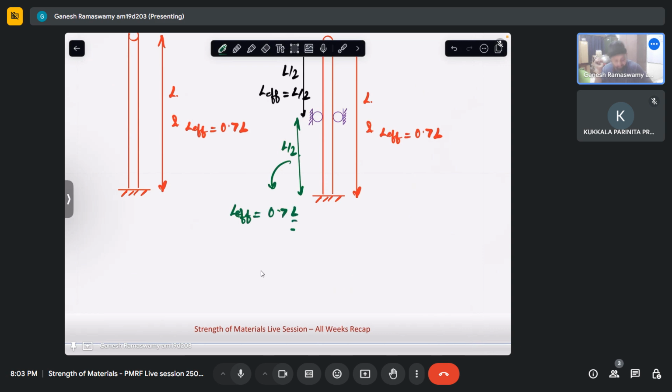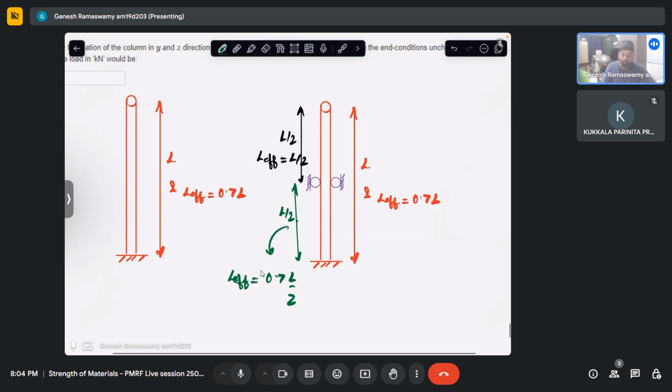Now how will we solve this? We know what is the critical compressive buckling load for the entire column. So if I were to calculate the critical compressive buckling load for both the portions of the column, top and bottom, given their different boundary conditions, whichever is least out of this has to govern my buckling. So this is all there is to constraining it in the middle.